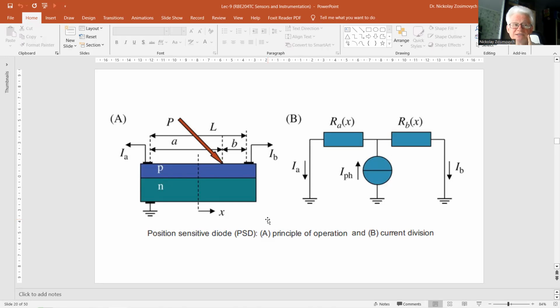And this should be considered when operating the device in that area. The range of a linear PSD is almost equal to its length, from several millimeters up to 10 centimeters. The width is a few millimeters. A two-dimensional PSD measures from 1 by 1 up to 4 by 4 centimeters. The total resistance between two opposing contacts is several kilo ohms.